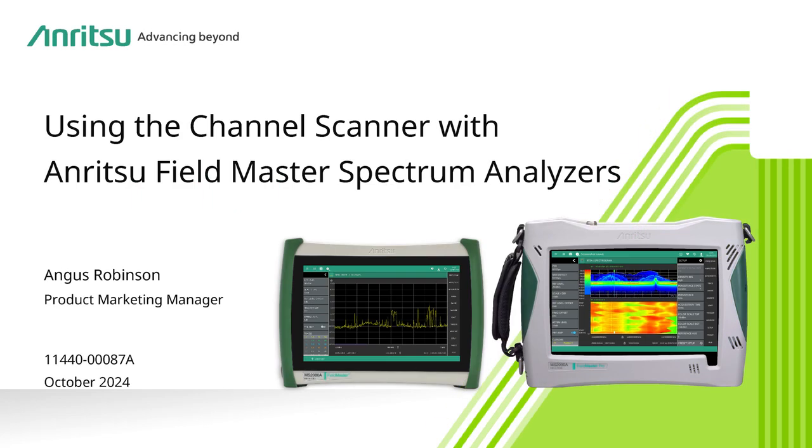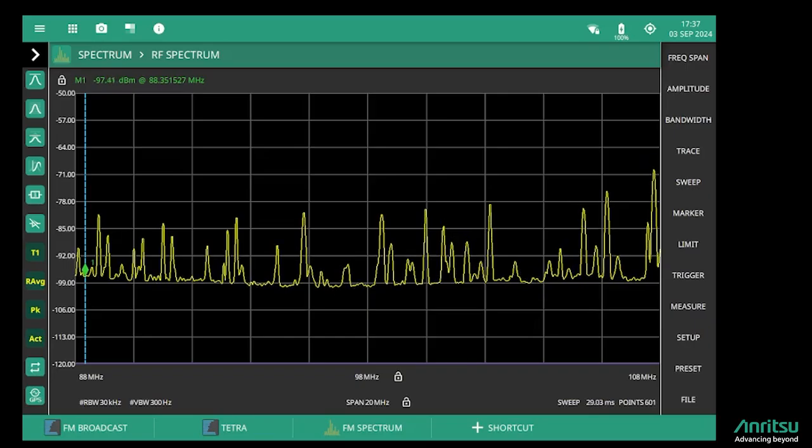In today's short video, I'm going to show you how to use the Fieldmaster channel scanner to monitor multiple signals over a period of time. The first set of signals we'll look at using the channel scanner is the FM broadcast spectrum, and here I'm in the standard spectrum analyzer mode, just monitoring all of the spectrum from 88 to 108 megahertz. I'm in the London area, so we've got a mixture of BBC transmissions, commercial radio, and there's actually a couple of pirate radio stations in here as well.